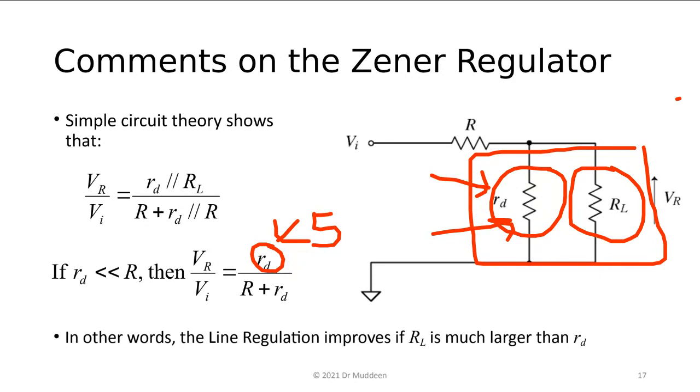Am I getting the power that I need? And that is the case here. If the diode you're using had an on resistance of 5 ohms, which means that the load probably shouldn't be less than 50, and the load turns out to be a 10 ohm load, then the diode regulator is not going to supply the voltage that you need. The system wouldn't function. You try to turn on the electronics and it doesn't work. So there are things that go back and forth a little bit, and you must always remember that.